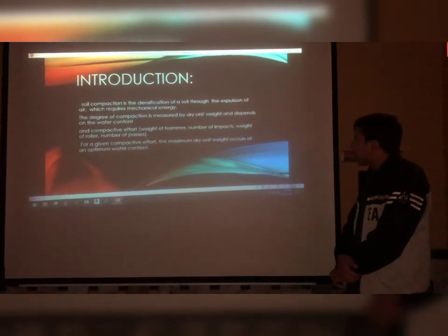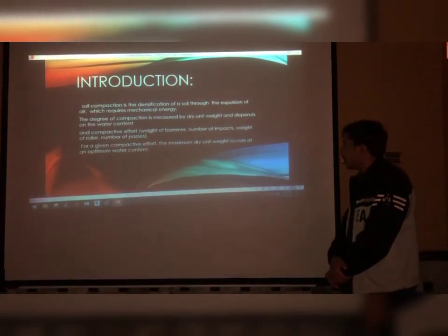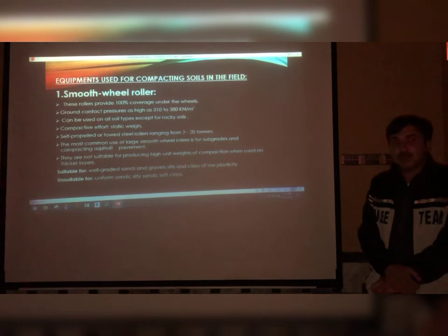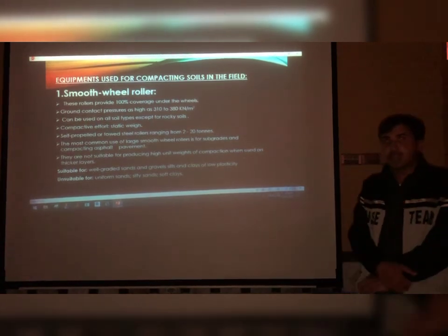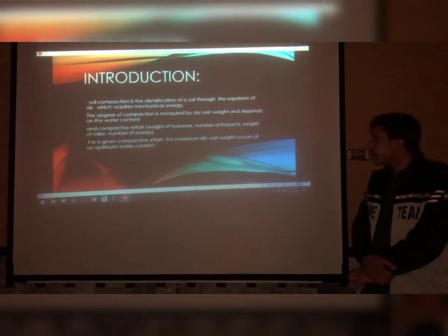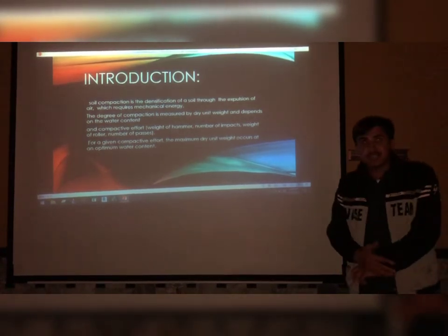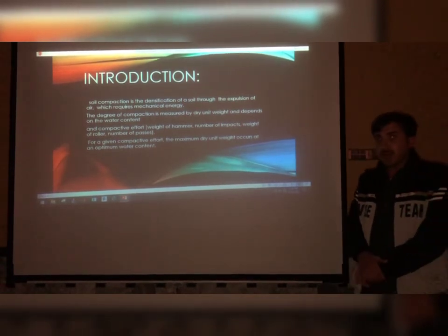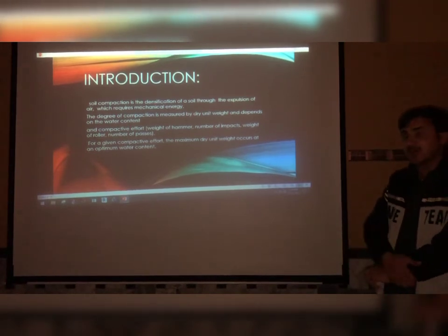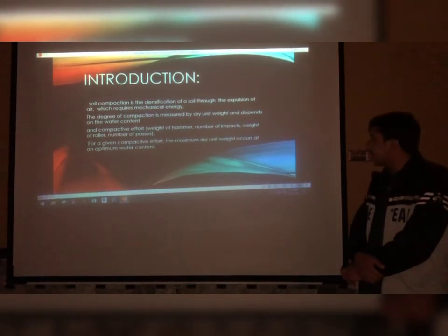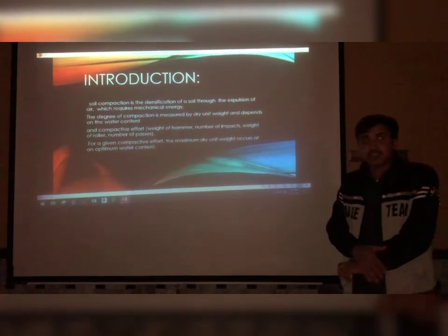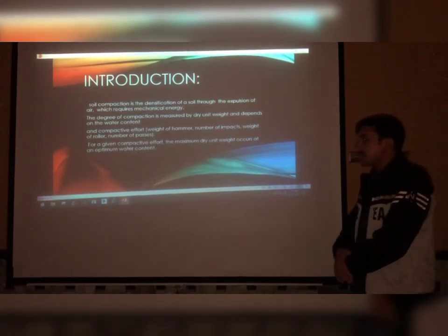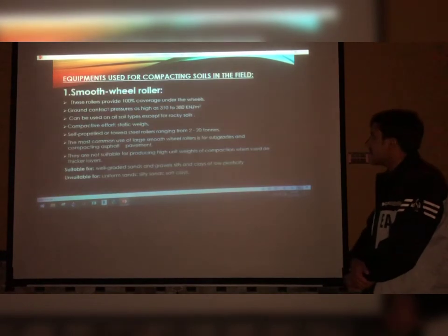For a given compactive effort, the maximum dry unit weight occurs at an optimum water content. Basically, we perform an experiment in the lab between the molded moisture content and dry unit weight. First, if we increase moisture content, then the dry unit weight will increase. One stage will occur. If we further increase moisture content, then the dry unit weight will decrease. That moisture content is called the optimum moisture content, and at the optimum water content we get the maximum dry unit weight. Next slide.